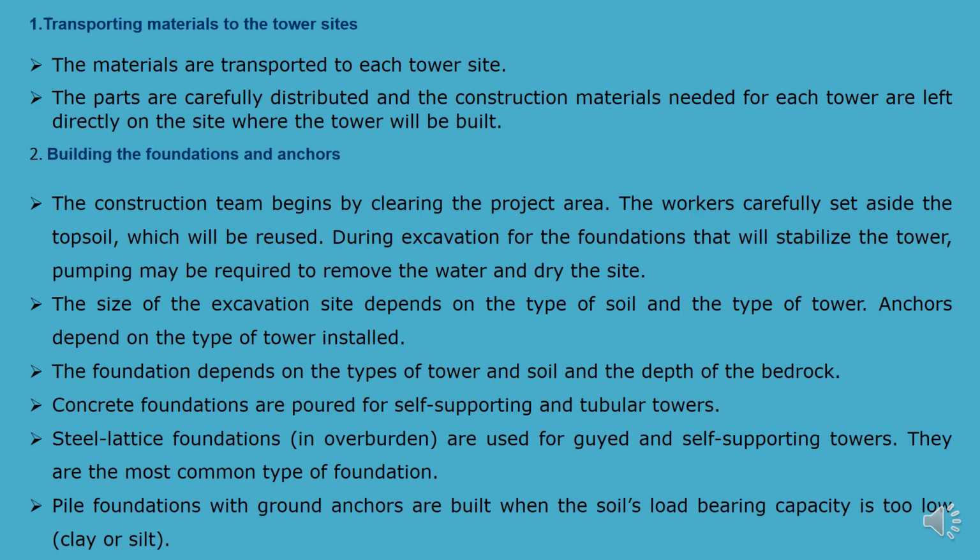So construction team begins by clearing the project area. Means we have to clear the site, right? So whatever the area is required, the project area is required, you have to clear the site. That is the first step. The workers carefully set aside the topsoil, which will be reused during the excavation for the foundation that will stabilize the tower. Pumping may be required to remove the water and dry the site, right? So during the excavations, right? So first step is clearing the site.